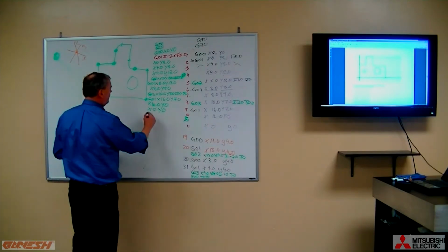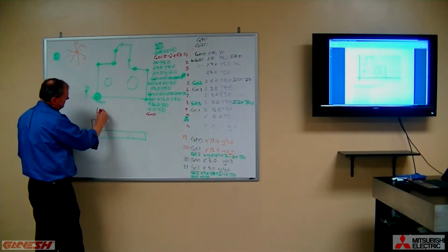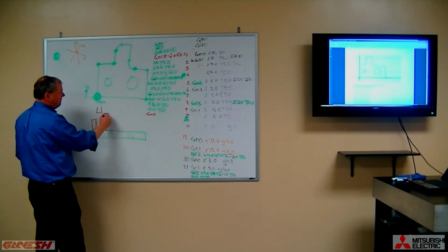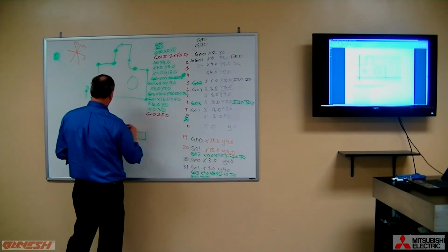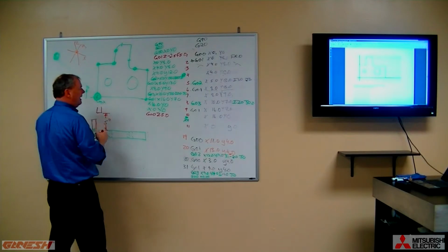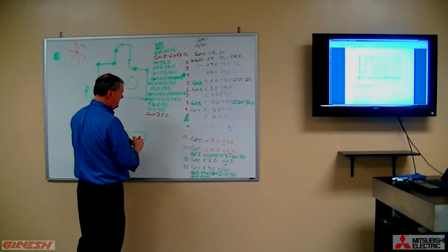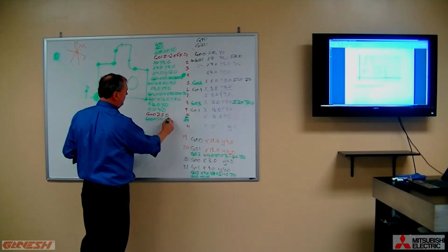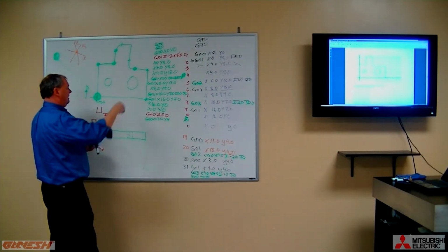So now I'm going to go and say G00, and I'm going to pick a spot that's about 5 inches above the axis origin. And we simply say G00, Z 5.0. So the machine moves up, and now we do our positioning to the point number 19. So I'm going to say here G00, X11, Y4. So now we're sitting up here in space, 5 inches apart.